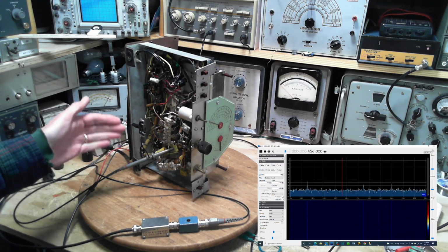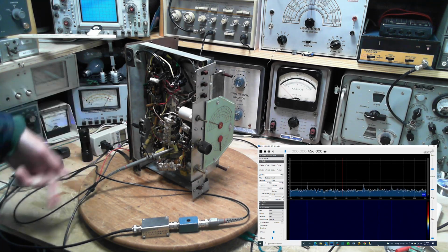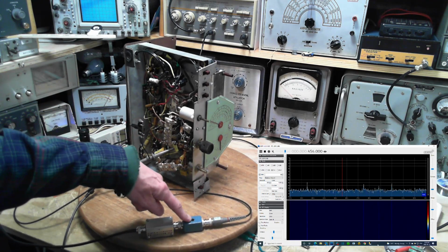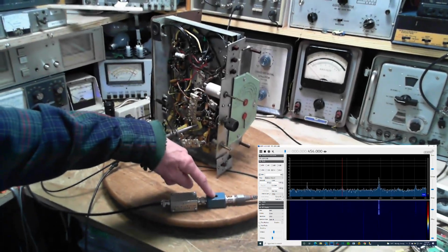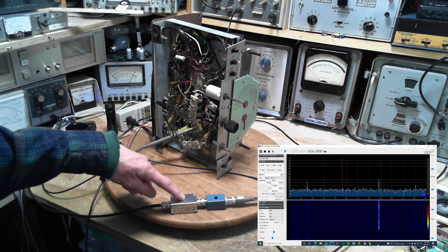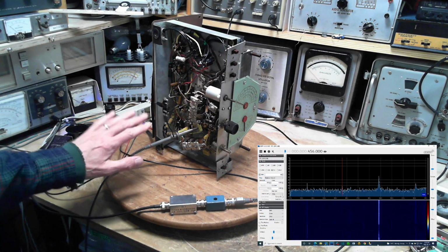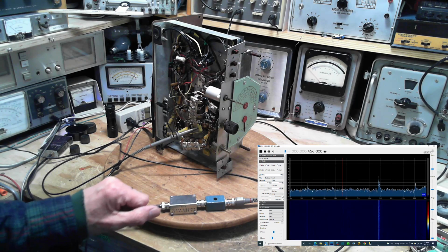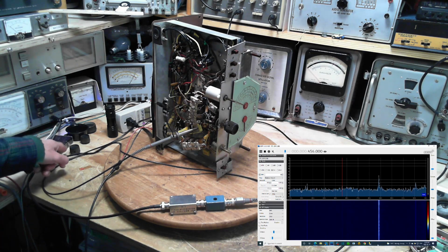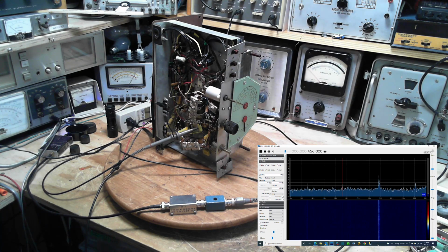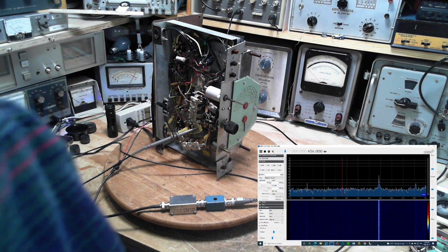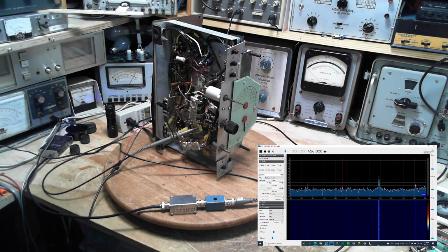Scope lead is set to the times 10 setting. Scope lead then comes through a capacitor here. There's a small capacitor in this box, and then this is an attenuator, a 10-to-1 attenuator. So I believe I've got at least 100-to-1 attenuation in this. And from here, it's going right into my SDR radio. So there's a bit of a risk here to the SDR radio, of course. It can only take so much on the antenna. So I think I'm okay though. That's famous last words. I think I'm okay.